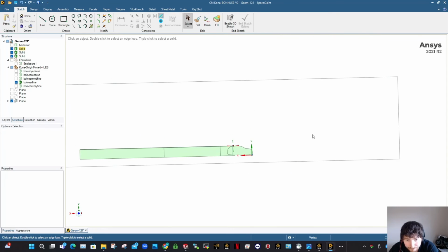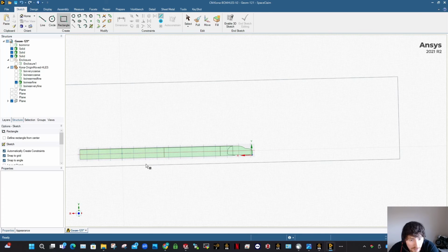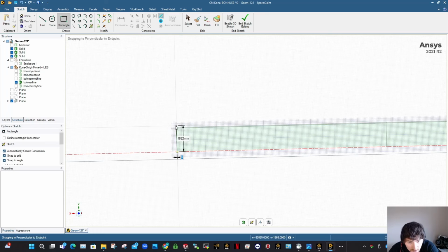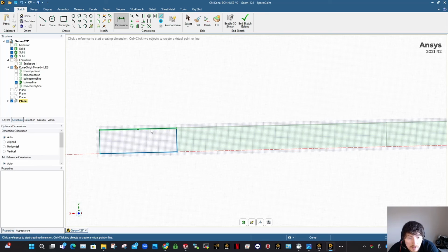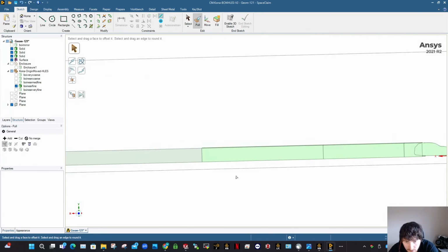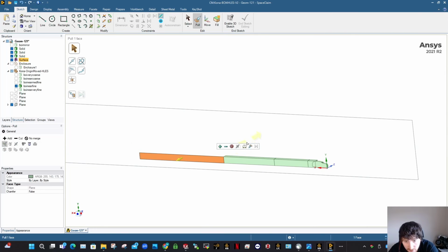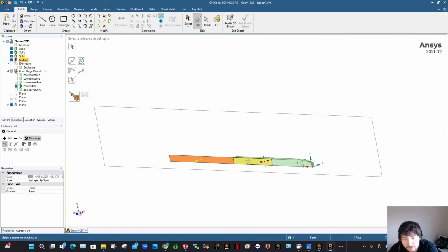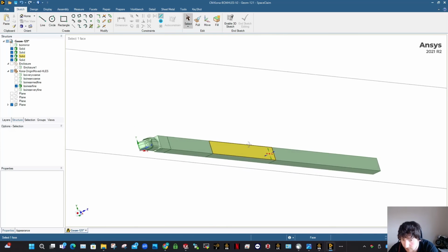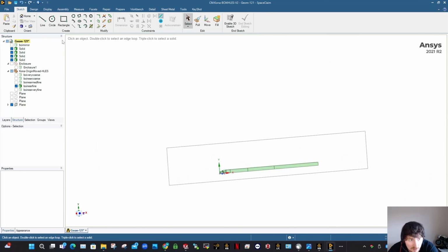And then the final one, this is your really far away wake, just to make sure, because the wake sometimes can be quite long depending on the vehicle. So that last one then is 25,000. And so these are, if the vehicle is 5 meters long, so that's 5L, stuff like that. And you can see the domain goes out to there, so I haven't taken up the whole domain.